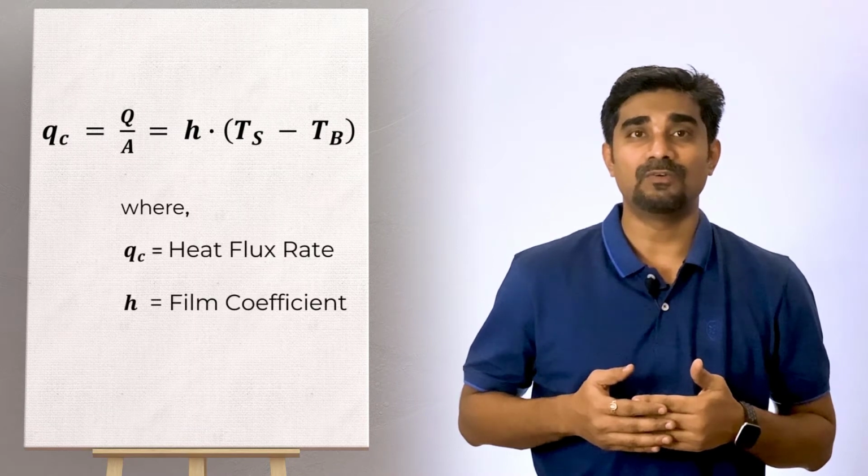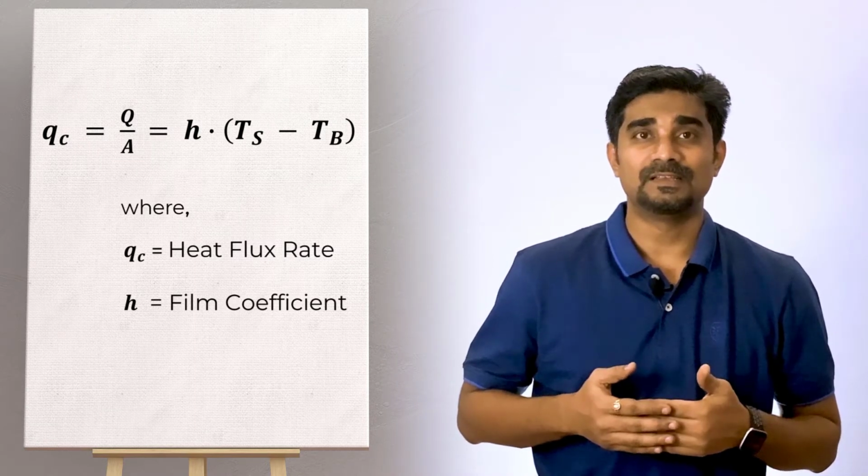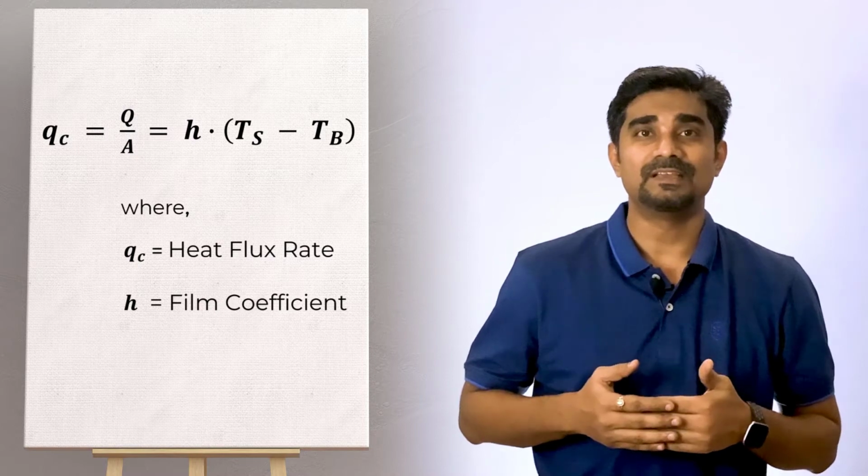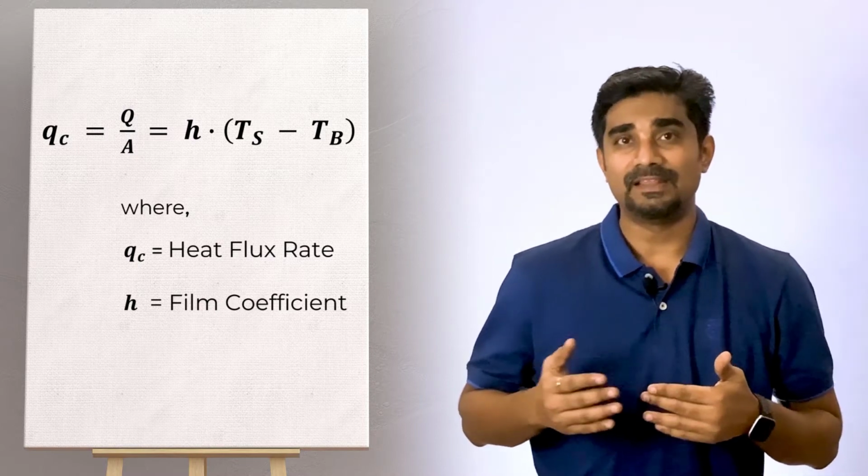When dealing with convection, the film coefficient, also known as the heat transfer coefficient, plays an important role. The film coefficient can be thought of as the amount of heat flux needed to cause a unit difference in temperature between the surface and the ambient temperature. Although the film coefficient may be dependent on many factors, having a temperature-dependent film coefficient is common in thermal analysis. Therefore, in this video, we will introduce how to define temperature-dependent film coefficients.